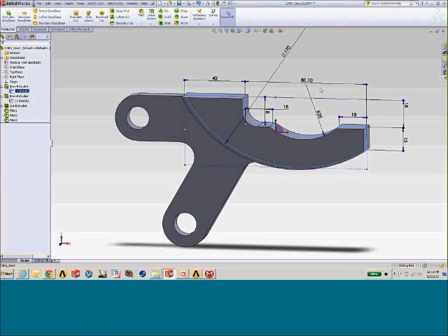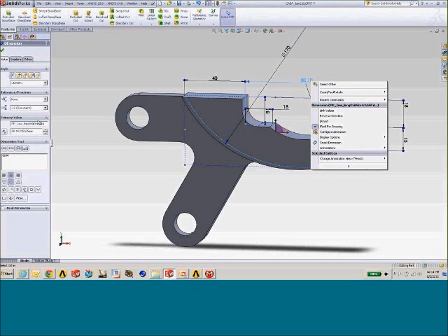Now, the way that I identify particular parameters to be brought in with the geometry is to look at the details of that parameter and then assign to it a name that I'll be able to filter out when I sweep through that geometry and pull out parameters. So in my case, I'm using a common parameter prefix of MP, so every parameter that I would like to bring into the analysis environment is going to have that prefix.